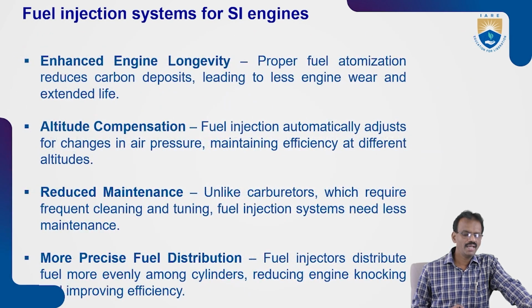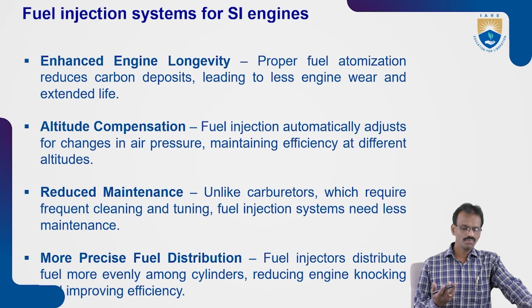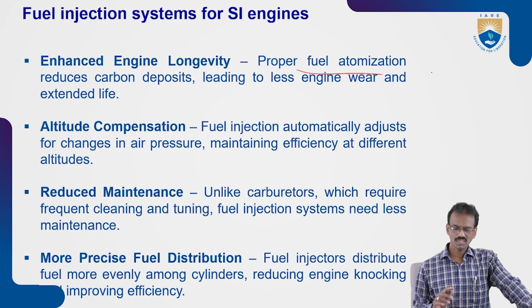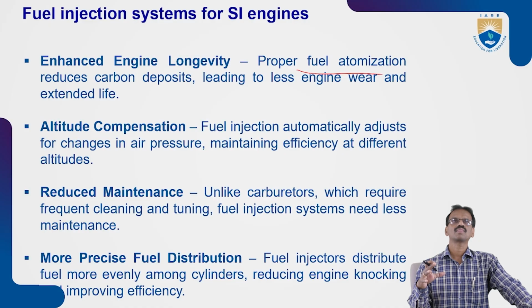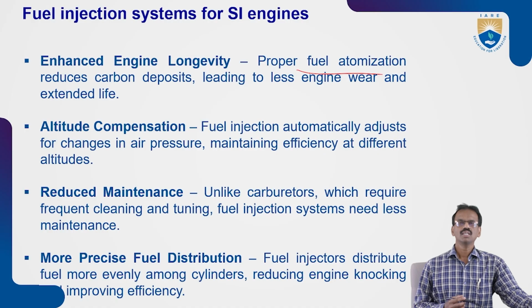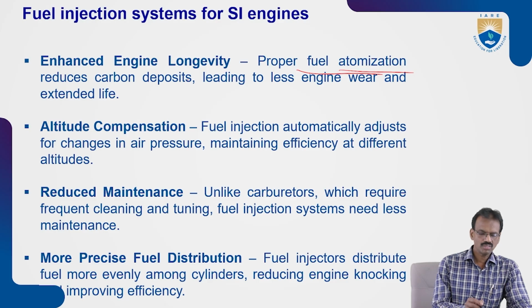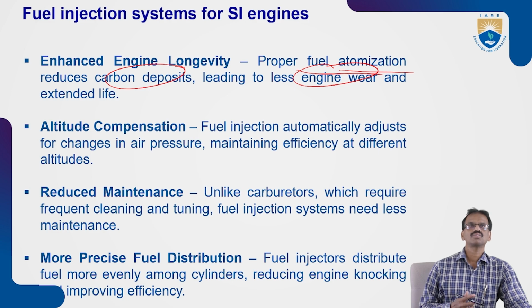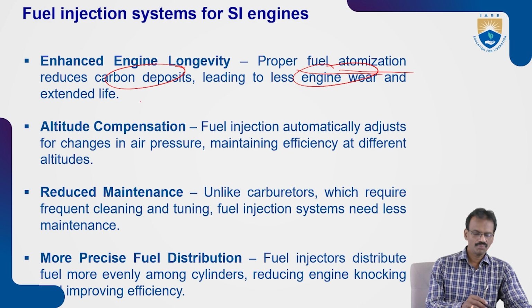So next, enhanced engine longevity. Proper fuel atomization, meaning big particles are converted into small particles. These small particles are enveloped with the air, which means proper air-fuel mixing. Homogeneous mixing occurs, which leads to an effective combustion process. Proper fuel atomization reduces carbon deposits, leading to less engine wear and tear, so that automatically leads to extended life.